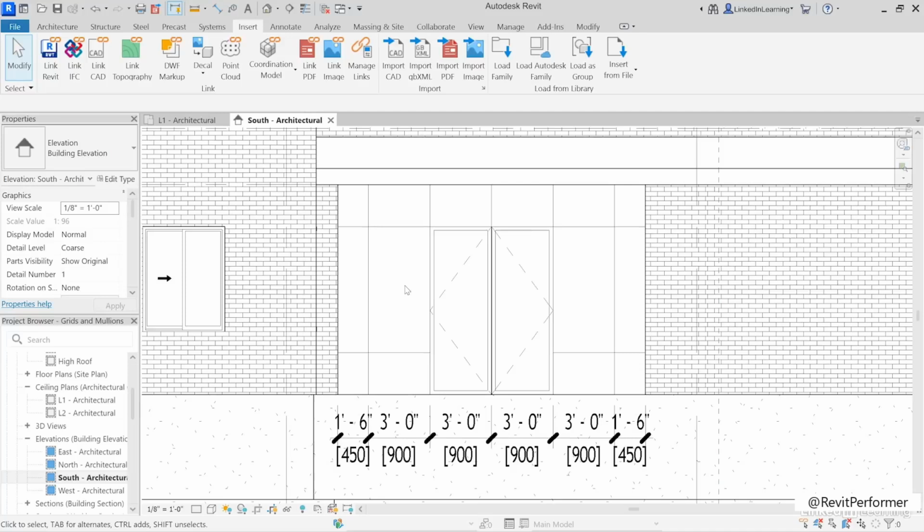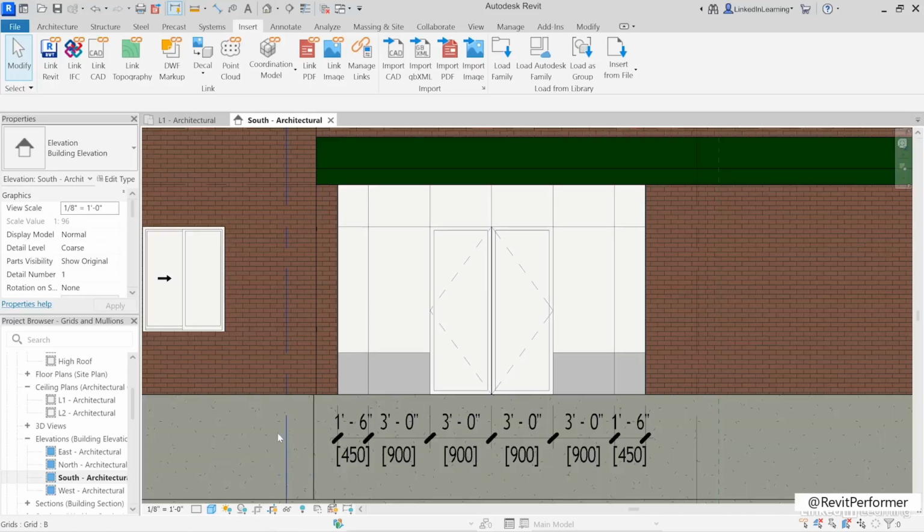Now, when you deselect it, it's going to be difficult to tell that we've made any kind of a change here. So let's change the shading mode in this view to make that a little bit easier to see. There's a visual style pop-up here. And if you choose consistent colors, it'll do a pretty good job of showing you that the bottom bay is now set to spandrel glass. Okay, so those are the panels that we need.